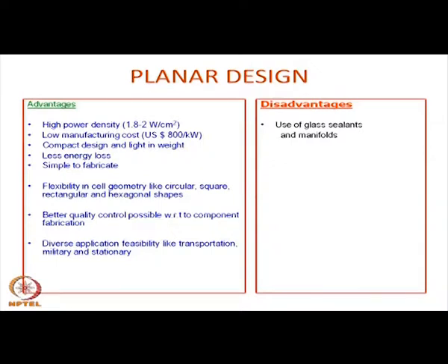Unfortunately, several glass compositions are available for this kind of purpose, but none of them are quite fully satisfactory. Either there is breakage because of thermal cycling, or there are reactions between the components. So that problem still exists, but a lot of development has taken place, and one can use some of the glasses available. Many of these glass compositions have been patented by different glass companies, including Schott from Germany.